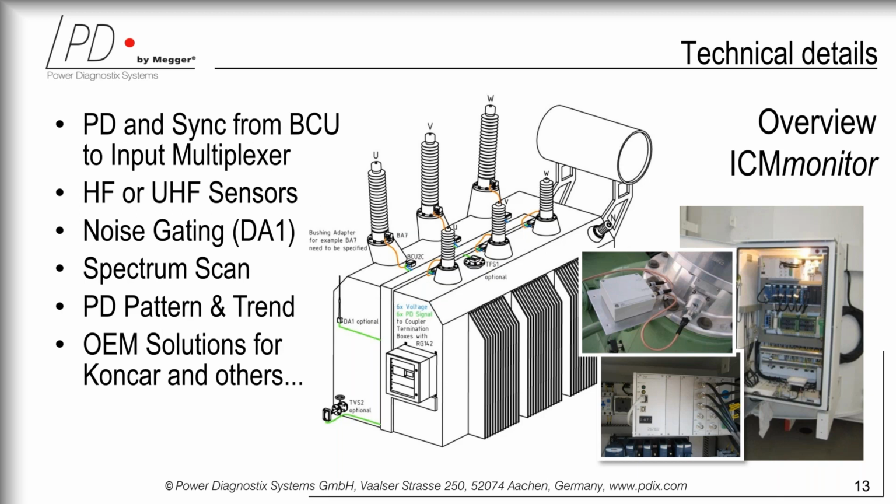There are a variety of companies that are purchasing such fittings from us because they would like to connect instruments to the bushing. There are companies purchasing such fittings just to be able to read what's happening with the bushing, but most people will continue by installing the box that you see here connected to the Teflon cable, and this box is able to split voltage and partial discharge measurements.